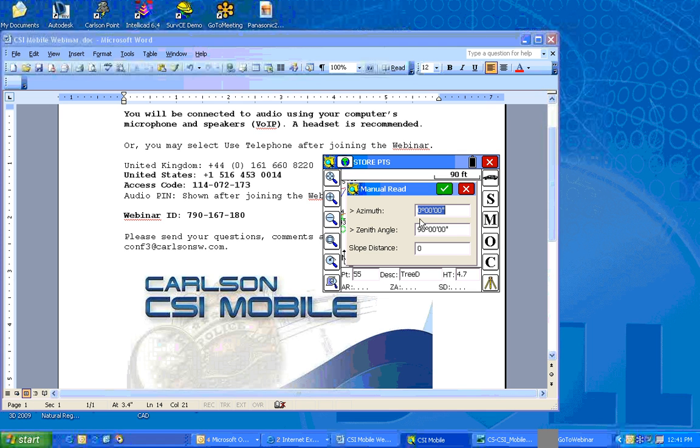We got one little issue running, and Terry and Romeo are seeing it, and they're seeing why it's important for us to even fix the manual mode. The azimuth actually, this needs to be taken care of when I do a move up. It works with a total station, but not in this sort of manual simulator, which is quite frustrating. If I go out 270, it's not going to be the 270 you expect. It's kind of like a 270 with respect to my last move up. And I really do need to have that taken care of, even in simulation mode.